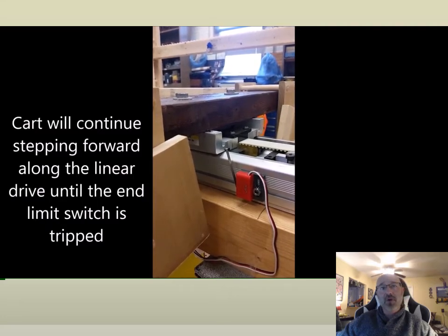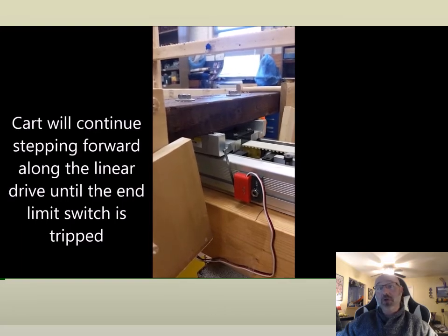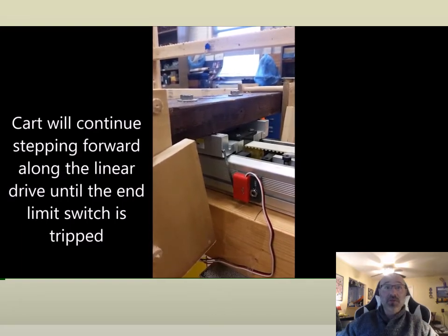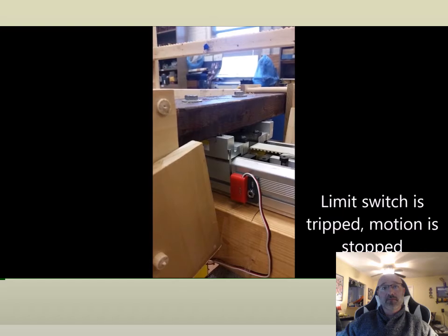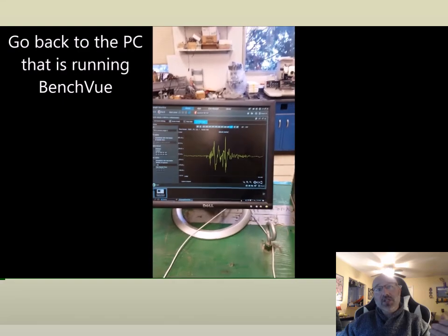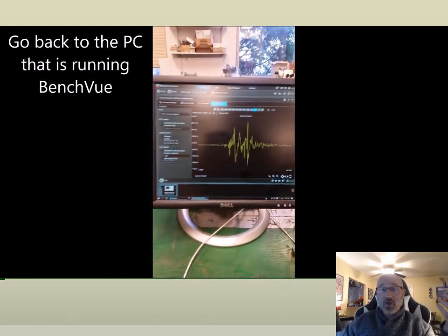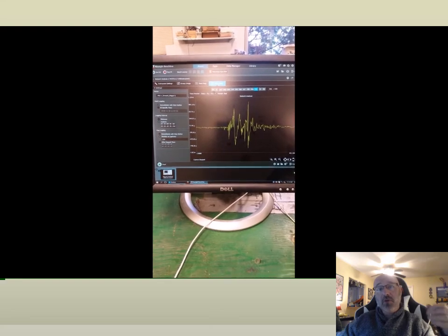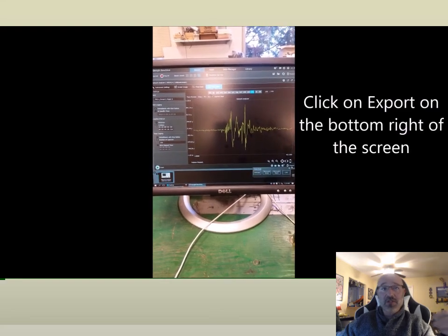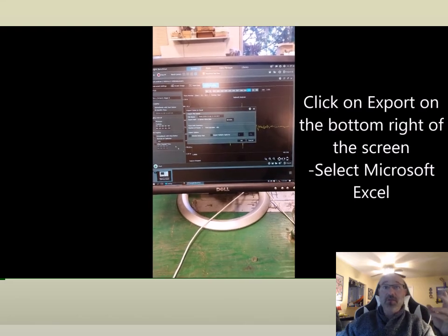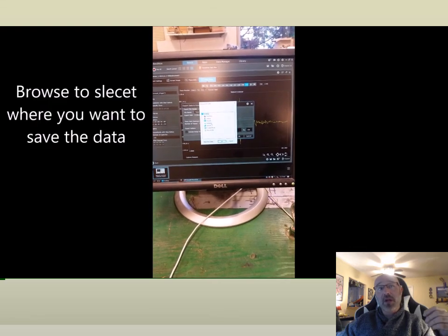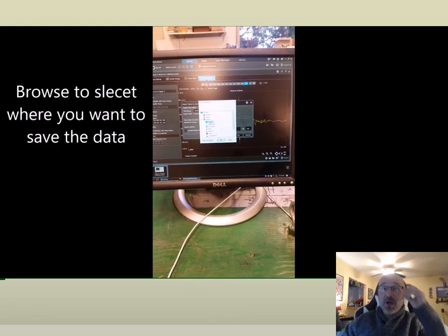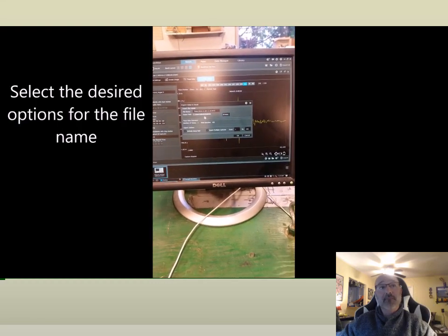So this is why it's important when we're designing these block diagrams, setting up our system, doing our coding, doing our controlling, deciding how many sensors we have. We need to take all of this into account. Therefore, limit switch is tripped, it goes to the next position. These vibrations and all these errors that occur during this are what's going to be disturbances. As we move on, we're going to look at some of these block diagrams and talk about these disturbances and how we can adjust for them. Maybe more sensors, maybe multiple sensors, averaging algorithms, things like that all of a sudden become very, very important in building these systems out and integrating different sensors into them.